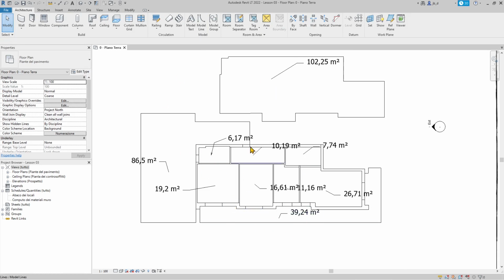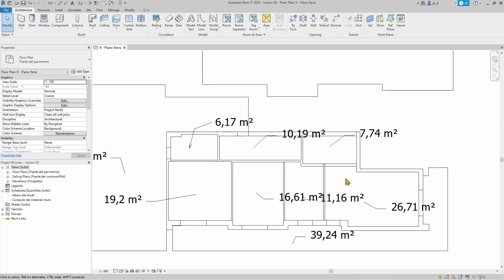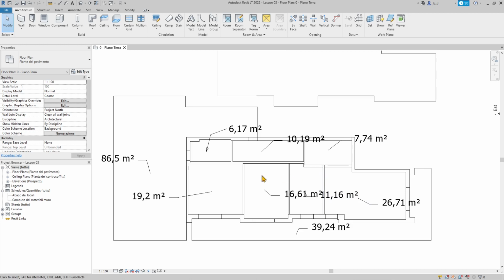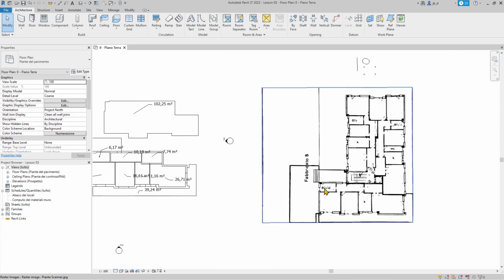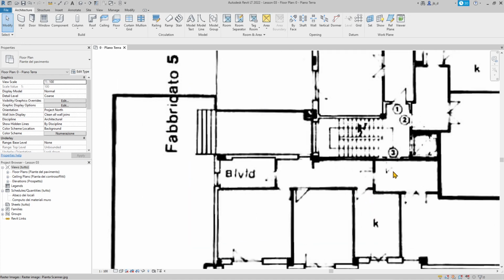Now you can see that this AutoCAD file is pretty simple, it doesn't have doors, it doesn't have windows, because essentially when you work in Revit, you don't need all of that. You're going to create them from the architectural families right here. So you don't need those drawn in the AutoCAD file. When you also need to do a retrace of a raster image, either in Revit or in AutoCAD, don't worry about all the doors and text and the signs and so on.